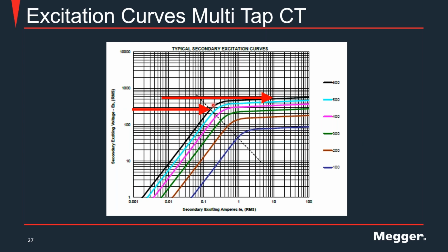See how the knee point is here, and if we go all the way down, the transformer is actually deeply in saturation. When it gets to this point here, this is when the transformer will start presenting, let's say, asymmetric saturation. And see the difference: in this case, we have about 280 volts, and the real place where the saturation is actually completely declared on the transformer is around the, let's say, 500 or 600 volts mark.